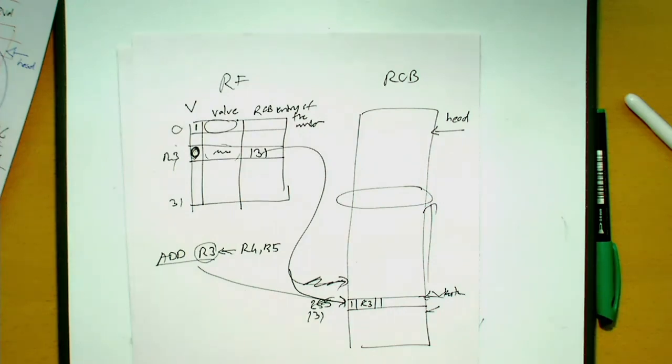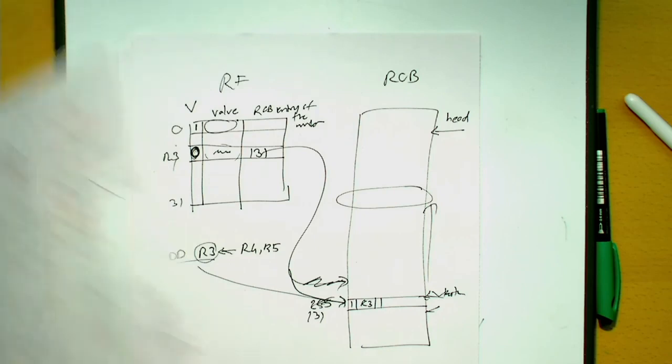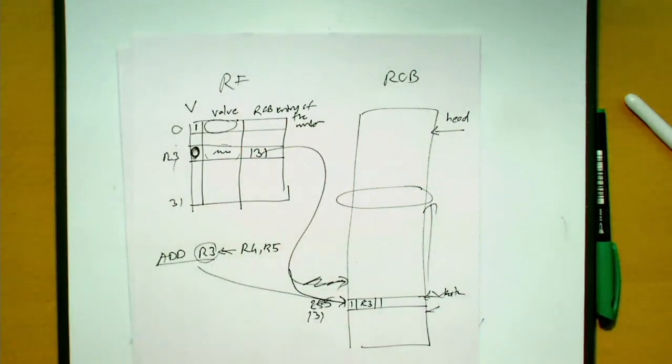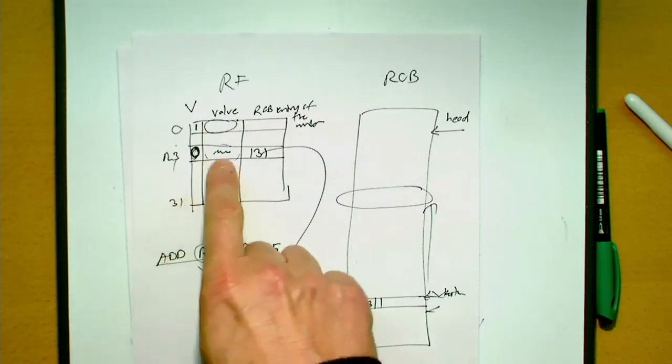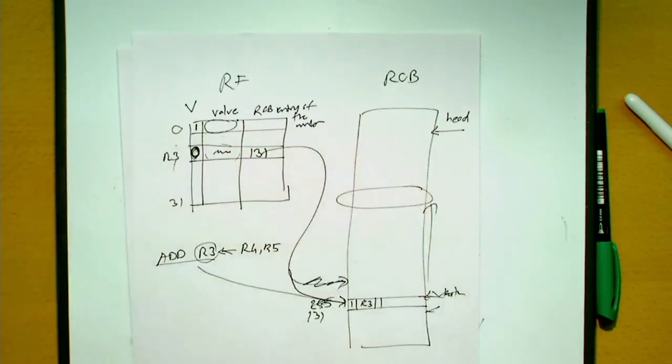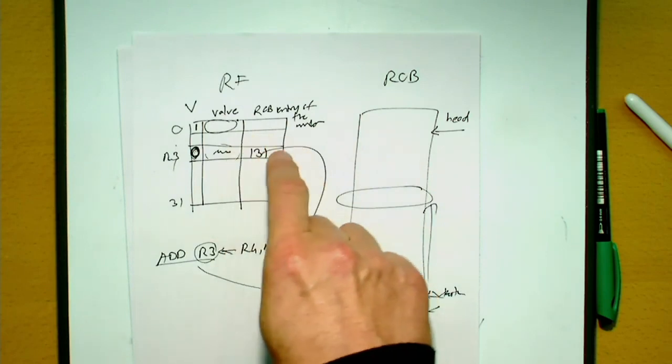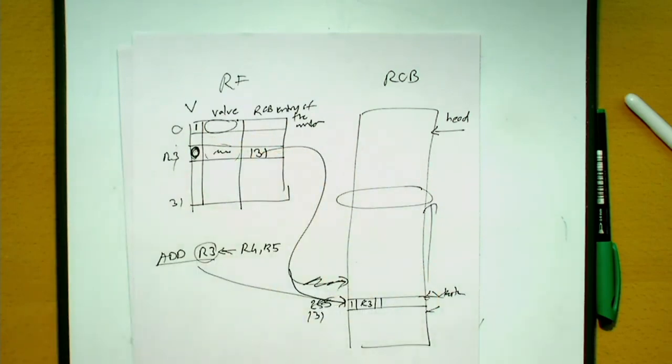Yes? So do you have to add more hardware to the register file? Like does each register have to be bigger now? No, well, yes, certainly. The location is now bigger, right? It's not just a 32-bit value, it's also the tag over here. I'll call this tag. It's a reorder buffer entry. But the register data value doesn't need to be bigger. Okay? So now you know how the reorder buffer behaves.